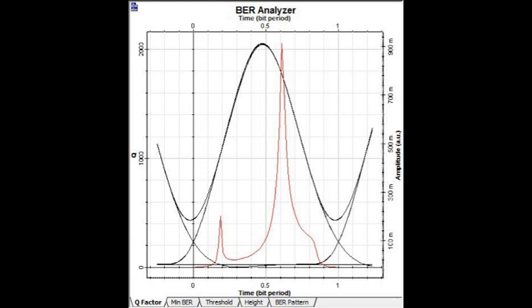Next is the analysis part of the result. For the first circuit, electrical without modulator, the analysis is done by changing the FSO channel attenuation and observing the BER analysis at different ranges. The wavelength used is 1550 nanometer with power 100 milliwatt. For the earlier stage, the attenuation of the FSO channel has been set to 15 dB per kilometer.